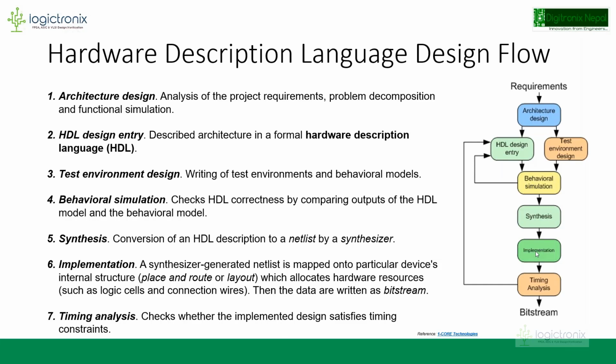The next step is the timing analysis. Timing analysis stands for checking the timing behavior: is the code meeting the timing requirements or constraints? If the code or the module or the algorithm implemented in the hardware description language design is meeting those, then bit stream generation can be performed. Bit stream generation generates the bit file. Actually, the bit file is the combination of hex codes.